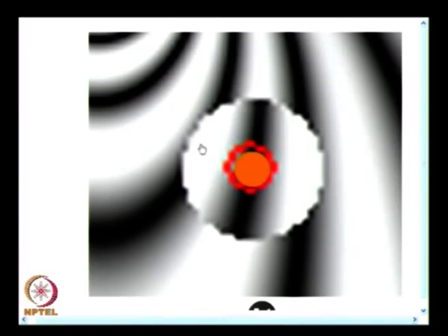What we have observed is that a higher fringe order has moved and occupied this position. So, what I have done is the compensation in a manner that whatever the fringe order is, here 3, minus that compensation will give the fringe order at the point of interest.